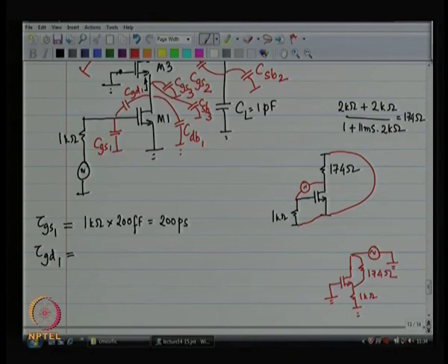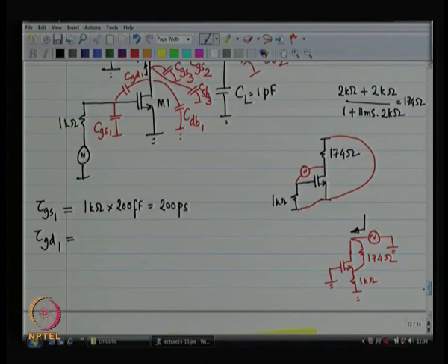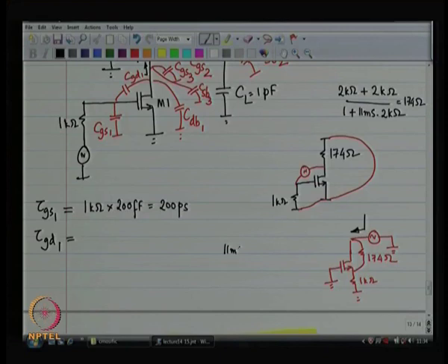All right. And as soon as you put it in this fashion, then the impedance looking into this over here comes out from one of our two template formulae, and the impedance happens to be equal to GM. Will you be getting just GM or GM plus GMB? GM and GMB are coming in parallel to each other. So, you will be getting 11 millisiemens